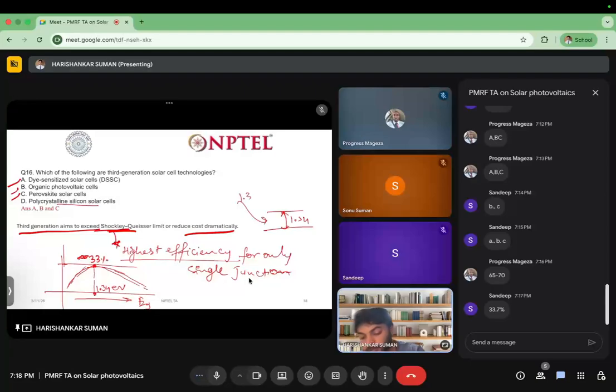If the light photon has energy of 1.35 eV or more, it will convert, but the excess energy will not efficiently convert into electricity, because higher energy goes to material heating and other phenomena. Only that much energy is required, or something a little more. So according to this band gap, you have the maximum number of photons in the solar spectrum.